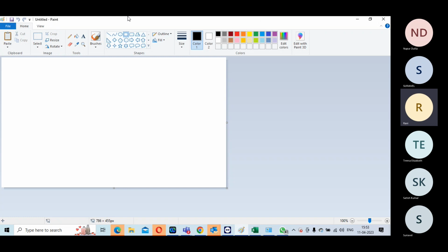One thing first, which corner should you use for CTS? The worst corner, because we are mainly preferring hold. My preference is hold. The best corner, see, this again is a dilemma. Typical corner. There's not one good answer, but the best answer is still this. You focus on your setup because that's your control. Run your CTS on the worst, but also check CTS on the best corner.